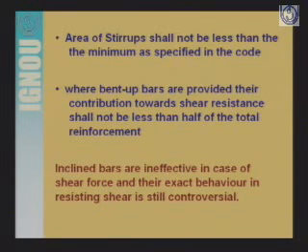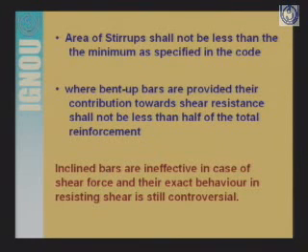Means, if there is under some cyclic loading or under the effect of some variable loading, if there is a reversal of shear force, then in that case these inclined bars are ineffective, and also their exact behavior in resisting the shear force is still controversial.